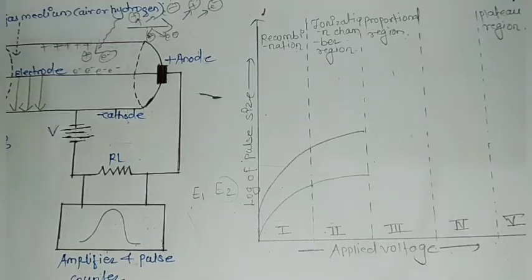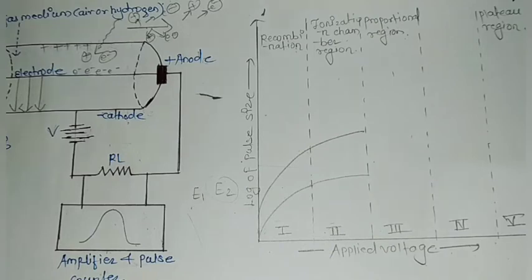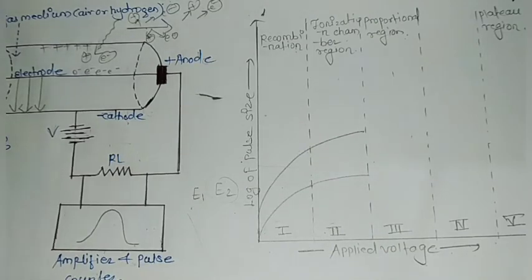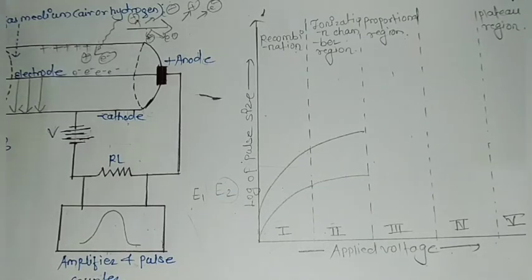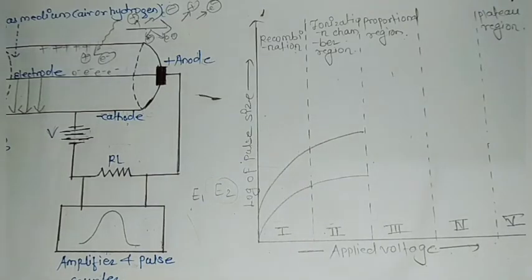So, these are known as secondary ionization. So there is going to be a cumulative addition to the total number of positive ions and electrons due to the secondary ionization happening because of this collision of the electrons and positive ions in the first place.